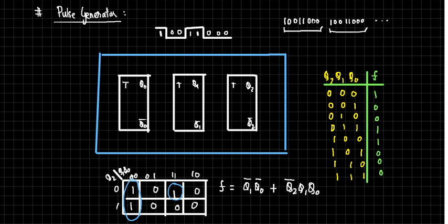Now what you need to do is simply connect that to an OR gate. How much circuit is required? One 3 input AND gate, one 2 input AND gate and one 2 input OR gate. That's it. Job is done. Simple, no? If someone asks you to generate this type of sequence, you should be able to do that easily. Tell me the connections now.